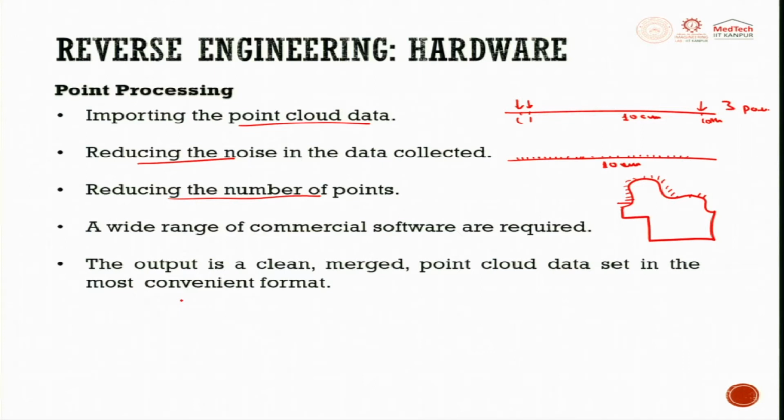Now, these tasks of measurement using CMM are performed using a range of predefined filters already. Multiple scans are sometimes needed to ensure that all the required points are scanned, and a wide range of commercial software is sometimes required to clean the data as well. The output is a clean, merged point cloud data set in the most convenient format.